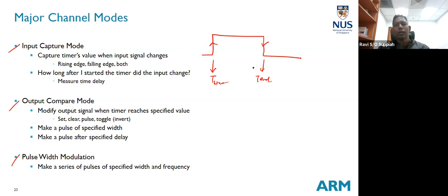Also can. All right. But your timer module also already has this capability, and it already gives you a count value, which means the hardware is already doing the back end counting for you. So you just need to know the starting value, ending value, and then based on your prescaler settings and your clock frequency, you can immediately know the elapsed time or the duration of this pulse. Okay, so that is input capture mode.